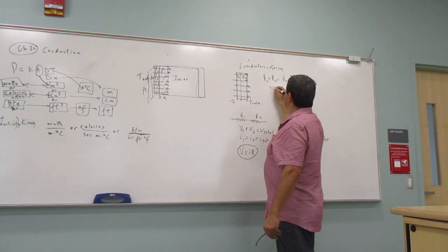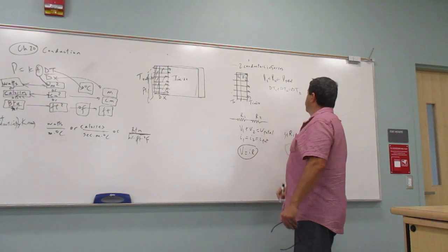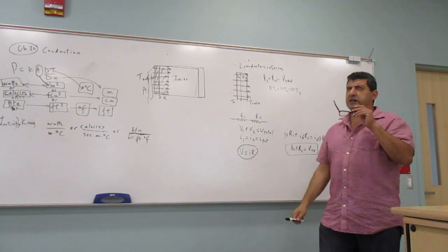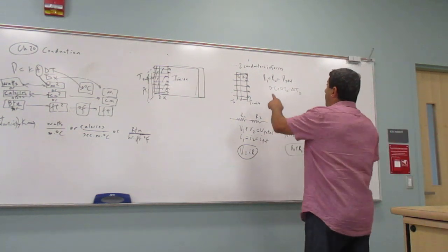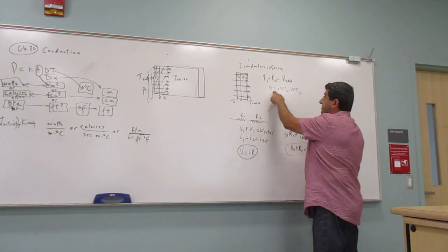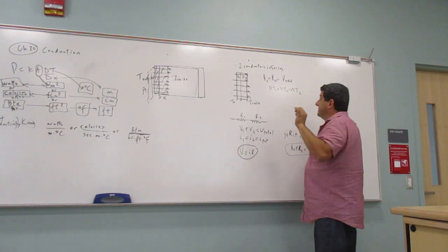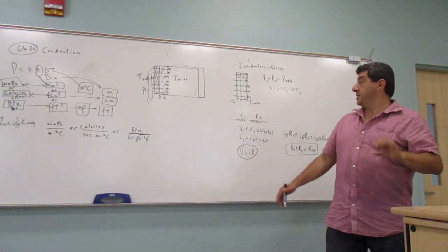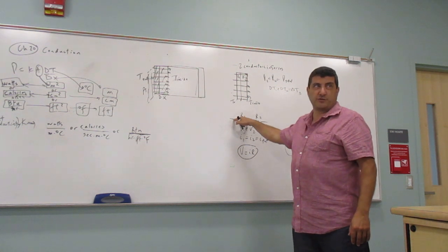So then we're gonna say delta T1 plus delta T2 is equal to delta T3. So the temperature gradient behaves like the voltage. But at first it sounds as if the power should be more similar to voltage, right? Rather than temperature difference. But if you think about it in depth, you will see that temperature difference should actually behave like voltage, because voltage across the resistor is what drives the current to flow through it, right?